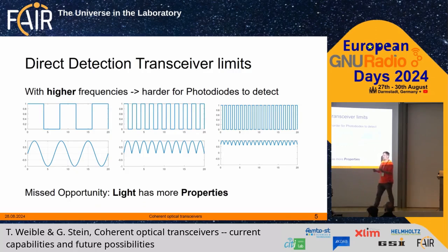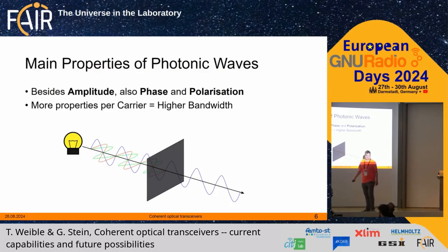And yeah, getting a little bit to, maybe you have heard of the eye diagram. What is the eye diagram? Usually when you have an oscilloscope and you have a frame that is moving with the signal and you are measuring the signal quality, what you end up seeing is a sinus wave upwards and a sinus wave downward at the same time. Just imagine you're folding it a little bit and you have like an O here, and this looks like an eye. And if the signal is not precise enough, you start to see odd points there and lines and so on. So that is one thing.